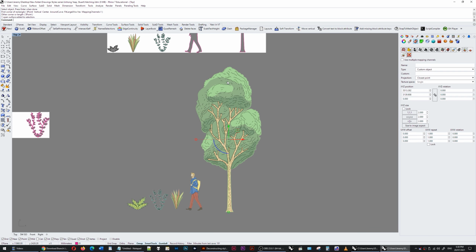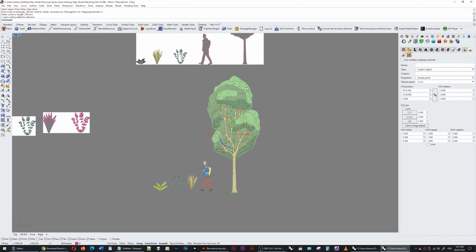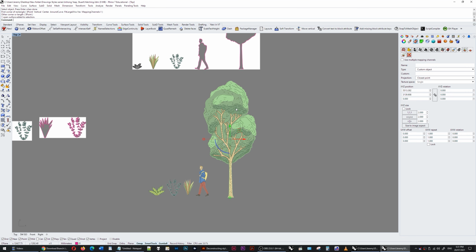What this does is this applies a custom UV mapping to the surface, which may help later on during the rendering process. In the rendering process using Rhino cycles, on a couple of occasions I have found that the cutout surface completely lost its original positioning from the original image. It would try to compress the whole image into that one cutout surface. Applying that custom mapping should help to prevent that scenario.